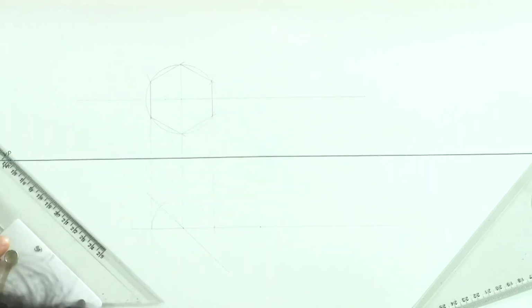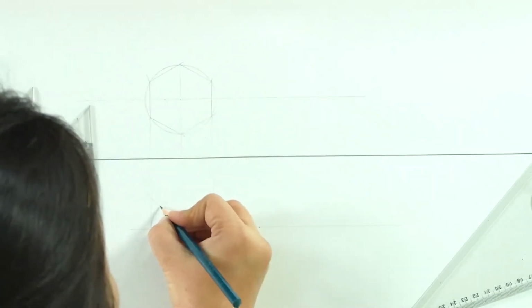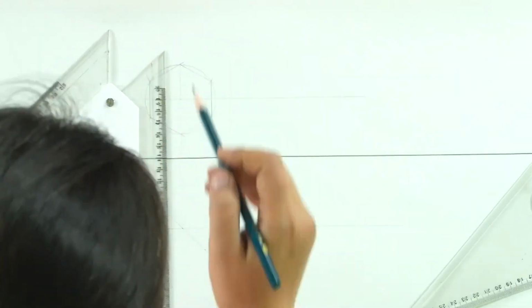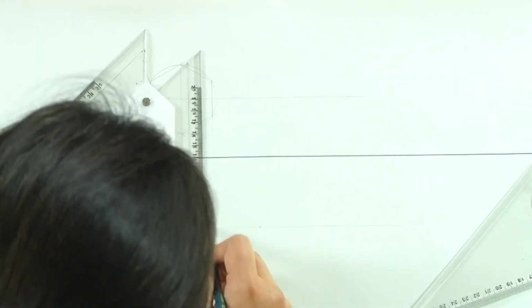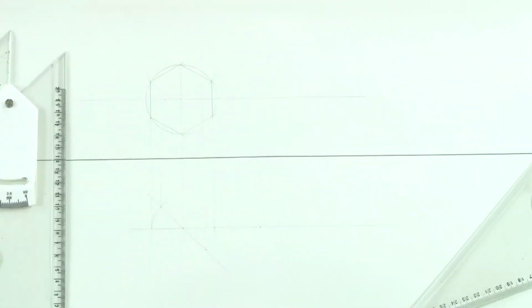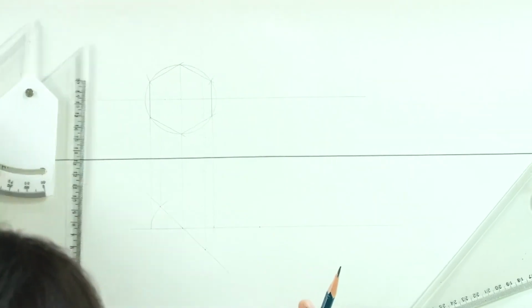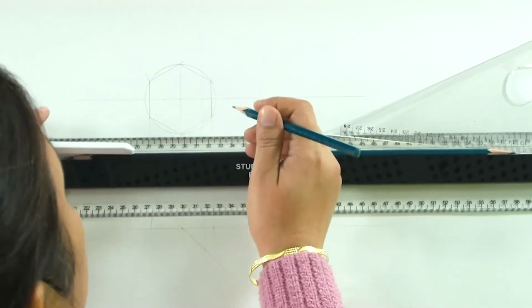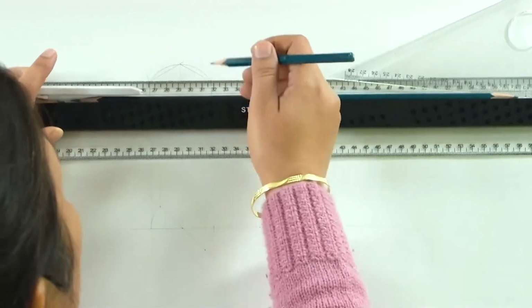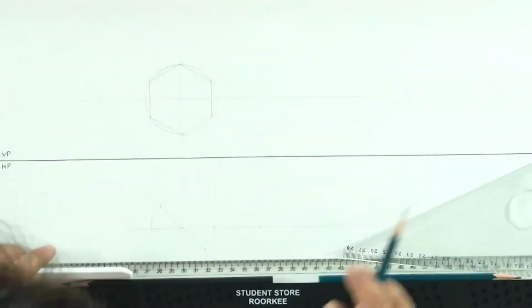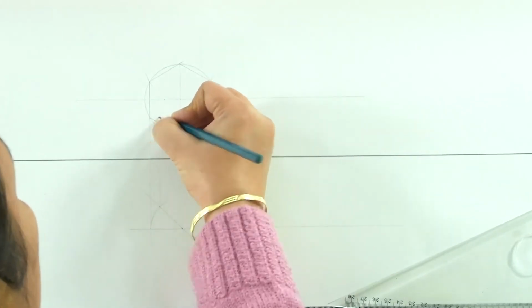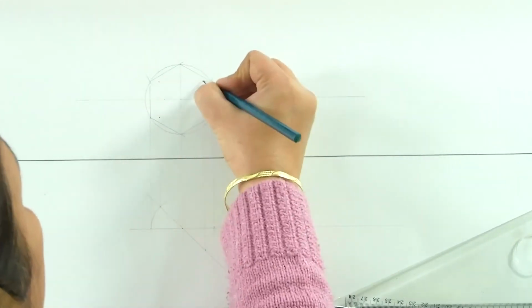So what happens? We get the new points here in HP, and now we take their projections back to the VP. In this case, the vertical projections, they remain the same, and here we will have the same horizontal projections coming, which is how we have done earlier, and the new points that we get are these.